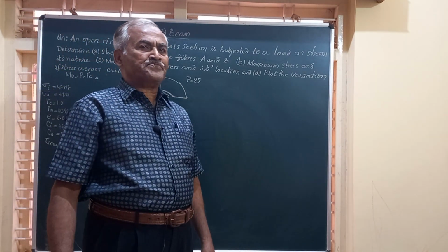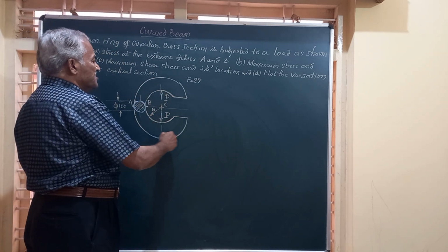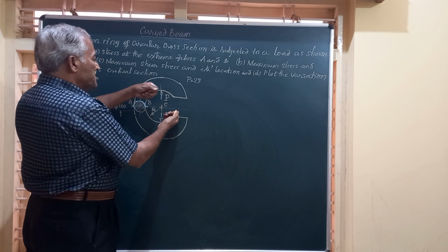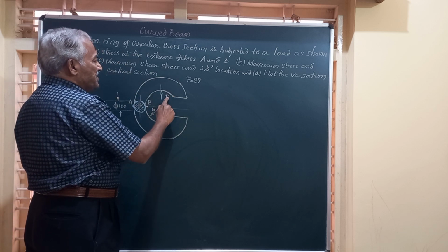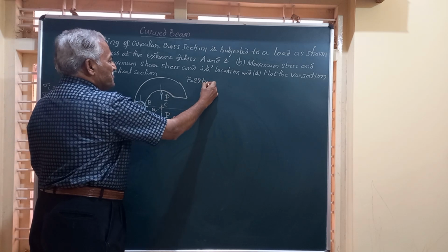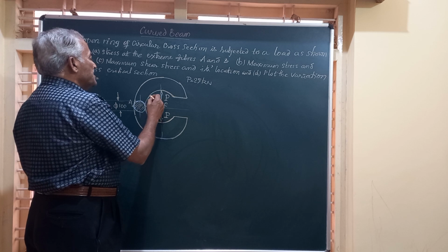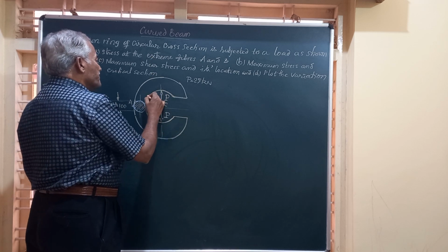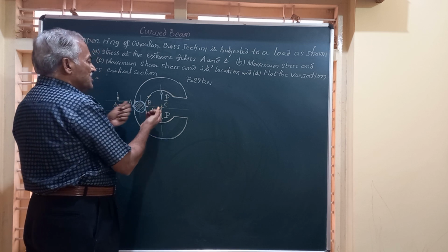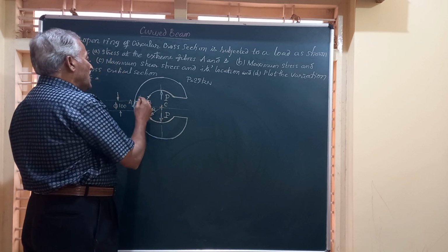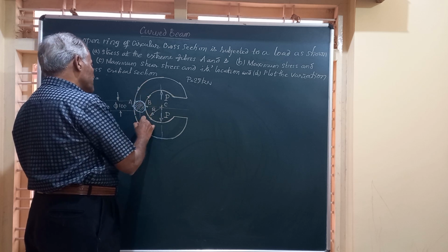Friends, if you just take out this figure, the circular ring, when this is being pulled by this pull P of 25 kilonewton, it's very obvious that the inside member, that is the inside fiber at B, undergoes tensile force, and the outer fiber A undergoes compression.